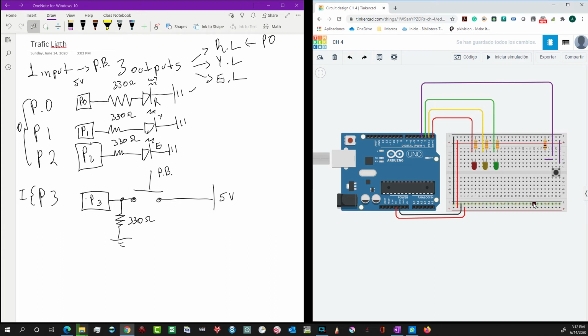The same goes for the red line. I get electrical connection from positive 5 volts to all this line, and thanks to these wires, red and black, I have the positive connection from here to here. And now again I get all these connections on the red line. The same goes for negative. Here I provide negative connection and I get negative or ground in all these connections.